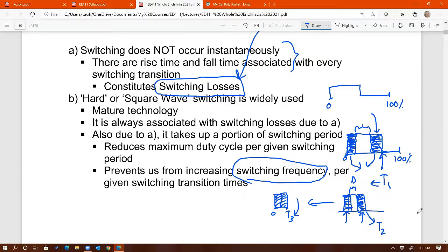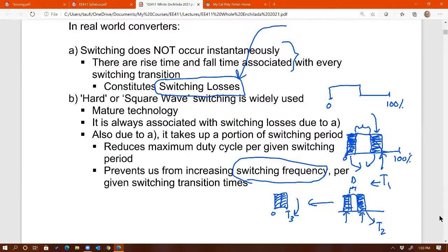Any question on this? I had a quick question. Yeah, go ahead. As your frequency increases, does your potential duty cycle decrease? Yes, exactly. Okay. It'll be harder for you to maintain duty cycle because then you have smaller and smaller space to work with, right? Smaller and smaller time to work with.